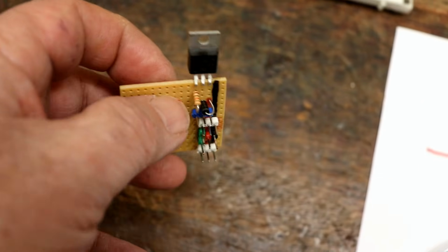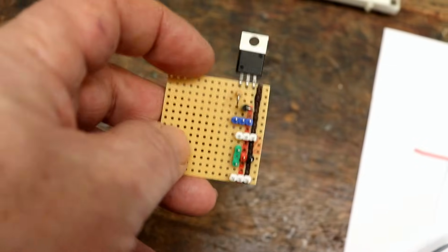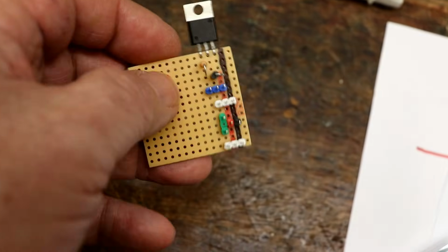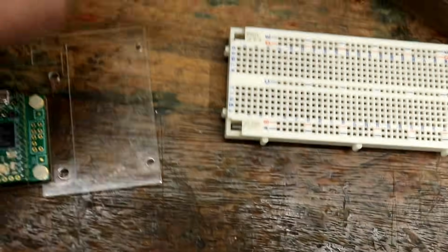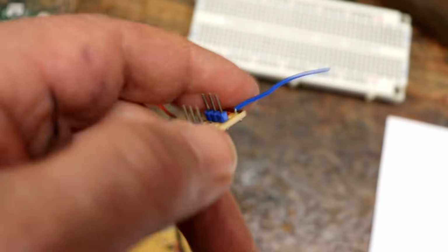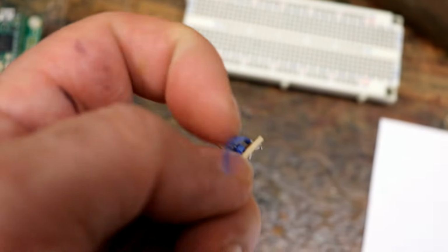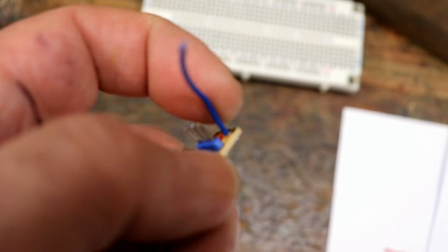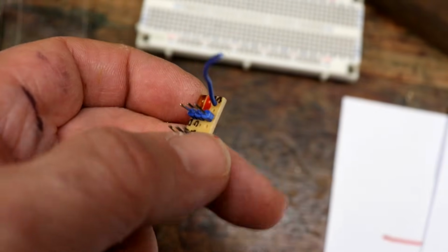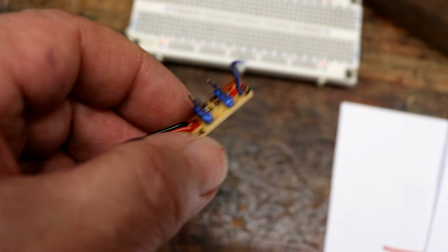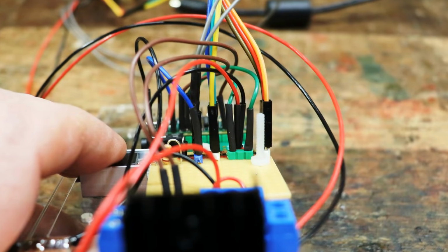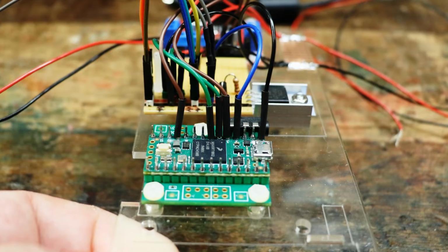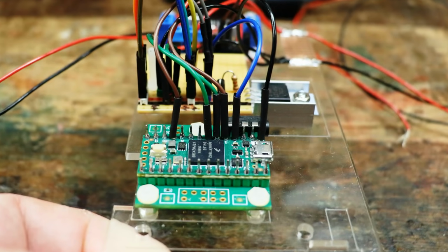Rather than having wires just going straight into the prototype board, and the problem with doing that is they're very weak, because once you've bared back the insulation, even not that much movement, and it's all focused on where the wires actually enter the circuit board, and they can snap quite easily. Whereas if you solder them onto header pins and then have a little bit of heat shrink sleeve over the top, it's really structurally sound and makes a good connection.